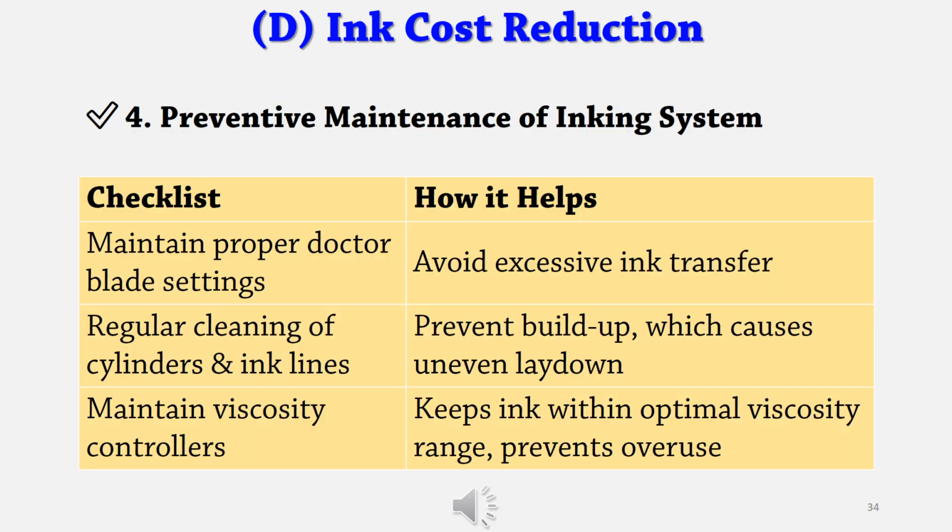Preventive maintenance of inking system can help you to reduce ink cost. Maintain proper doctor blade settings to avoid excessive ink transfer. Regular cleaning of cylinders and ink lines prevents buildup which causes uneven laydown. Maintain viscosity controllers, which keep ink within optimal viscosity range and prevent overuse.